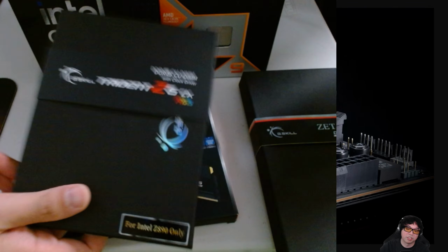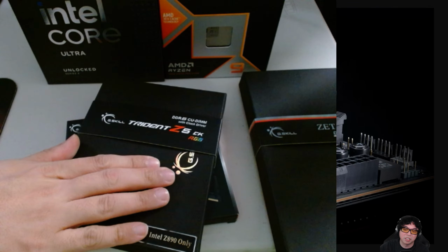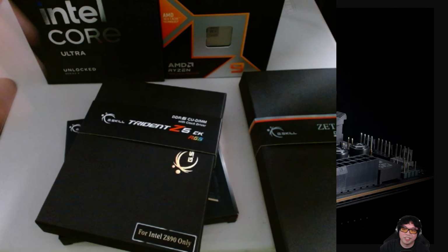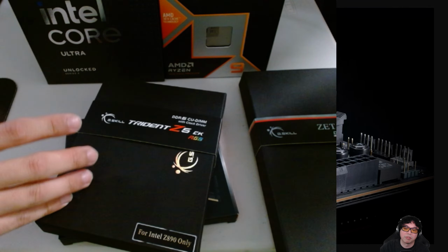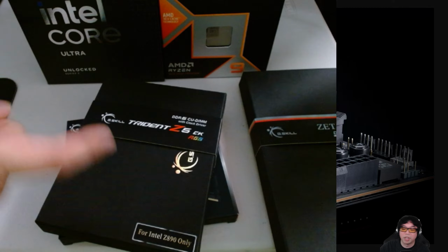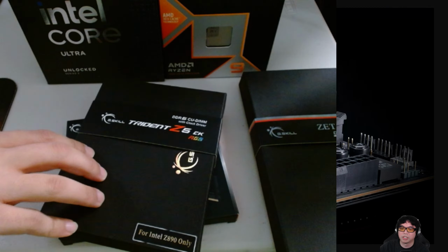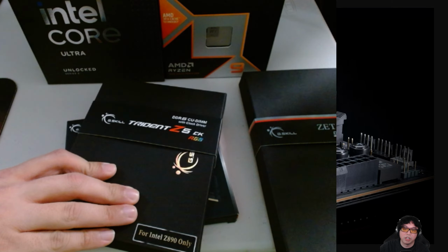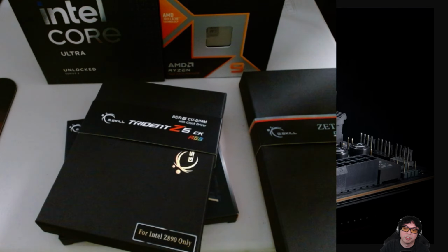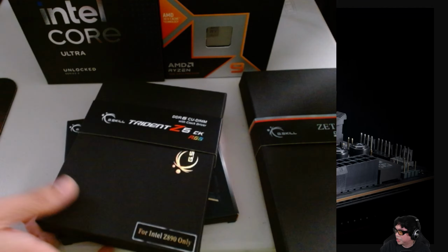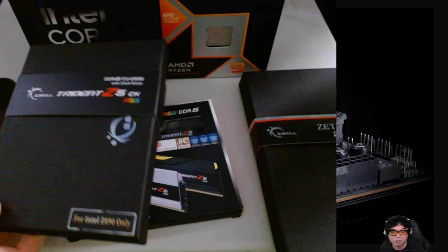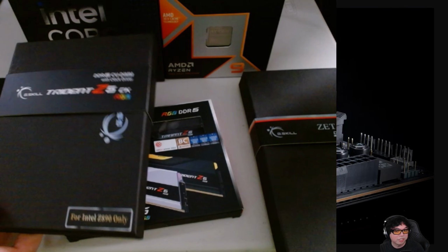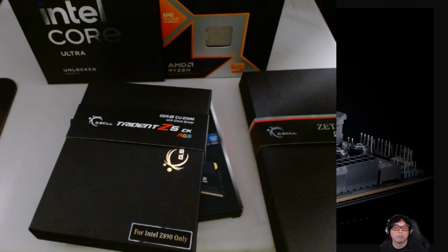This kit works fine. I was able to boot these 2 sticks on the Z890 Maximus Hero with the Intel Core Ultra CPU, and I could run the XMP. This particular kit is rated for DDR5-8200 megatransfers using the CUDIMM, so basically the clock driver, in single PLL mode. We'll talk about single PLL versus dual PLL versus bypass mode. There's a lot of terminology. This stream is going to be an extremely technical stream.